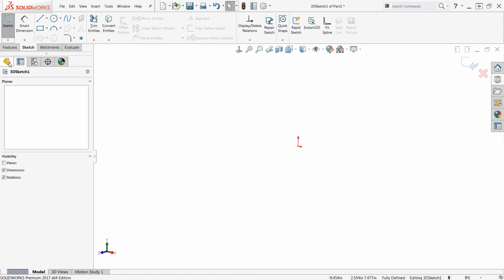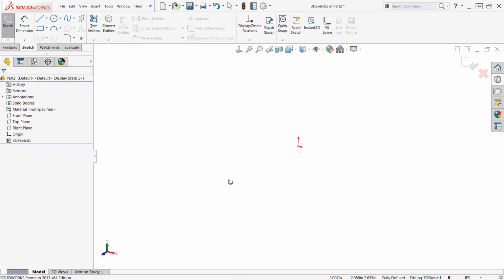All right, let's get back to our actual thing that I'm going to sketch here, right? What I want to do with this, and if you remember the PowerPoint that I just showed you a little bit, there was some sketch geometry on the top plane, basically at the origin. I'm going to use that to create this framework, because I want to create a framework here that I can insert structural members on, and I want to be able to control this thing. It's going to be a table, welded workbench or whatever, with a shelf on it. And I want to be able to control that with just a couple dimensions. Those dimensions will be based on my design intent of what it is that I want to do and control.